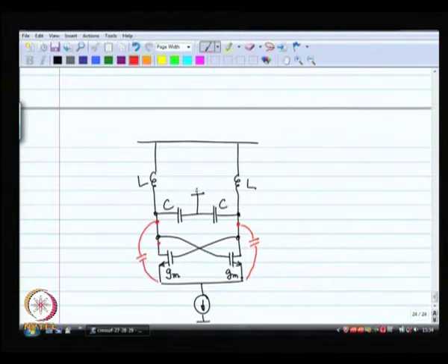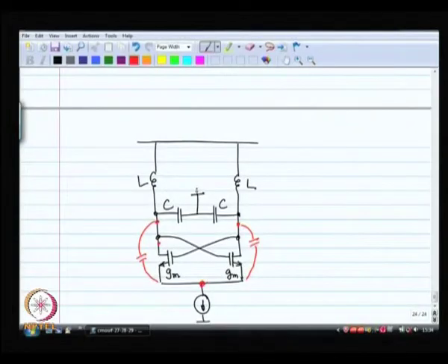If you recall the small signal half circuit model of this, this particular node is actually signal ground, and there is a capacitor between the output node and signal ground. So, it is actually coming in shunt with C. So, I do not need to worry about CGS either. What else is there?